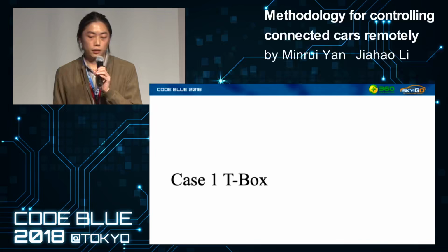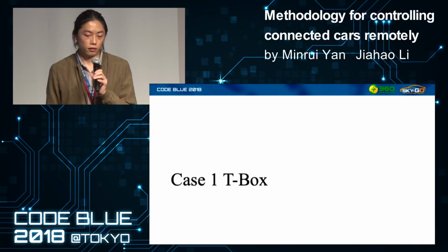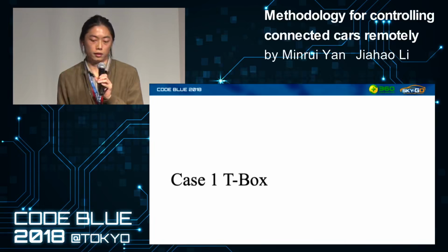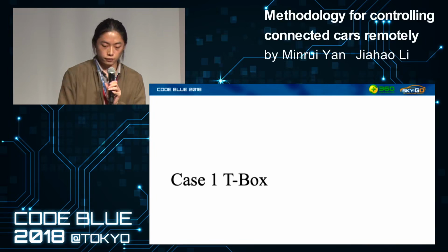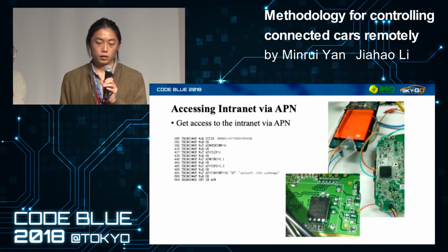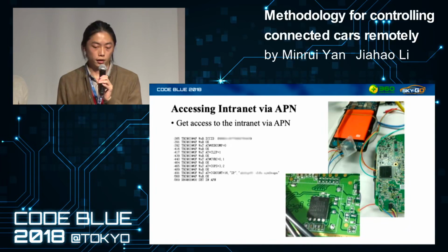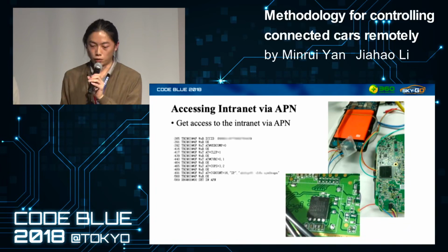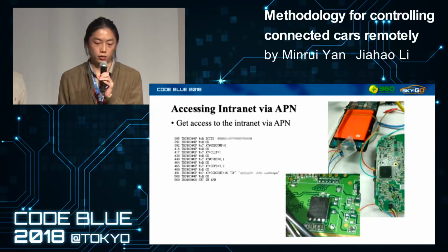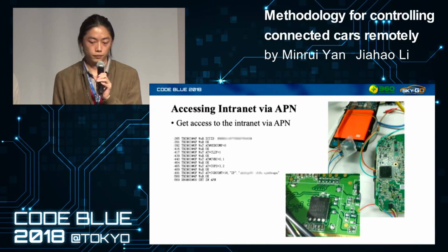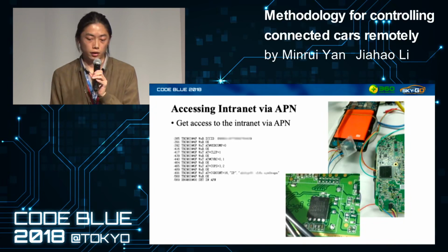According to the architecture and the attack surfaces aforementioned, we are able to hack a real car. Here are 4 real cases, and the sensitive information has been removed. There is another way to get APN configuration. We can sniff the UART communication between MCU and the LTE module. Then the AT command is printed on the console. It contains an APN configuration.